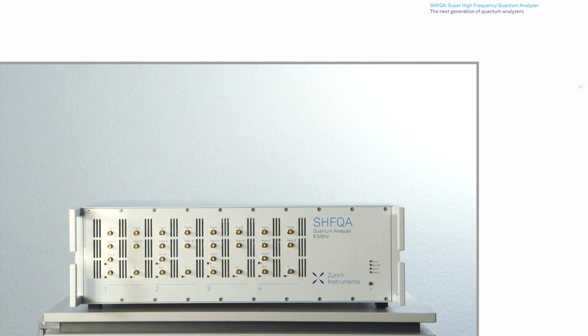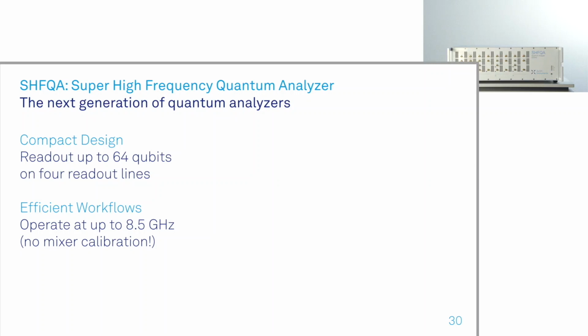First of all, it features 4 readout channels. Each channel can read out up to 16 qubits or 8 qubits. This corresponds to 64 qubits or 32 qubits for the full instrument. Next, each channel has the up and down conversion integrated up to 8.5 GHz. Importantly, we use an up conversion technique that is broadband, clean, and does not drift. This is in contrast to the normally used IQ up and down conversion technique. So with this instrument, from the first turn on, you will get a stable and clean signal, both in the signal generation, but also in the signal acquisition.